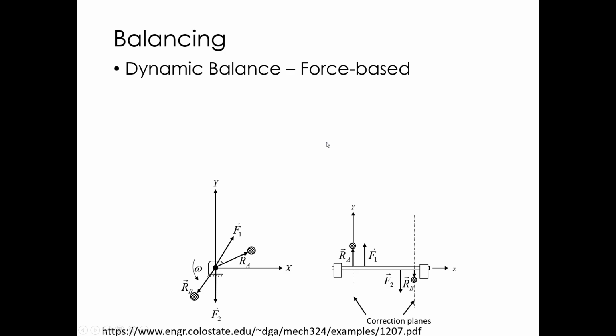Okay, force-based balance. The book does not do a good job on force-based balance, so I used an external resource here. You can see the link there if you want to see this PDF. But this is more useful. Force-based balance is how your tires are balanced. When you take them to a tire shop and they put tires on a balancing rig, this is what that machine is doing. If you're trying to balance a turbocharger impeller, this is what you do. If you wanted to make your own balancing rig, this is the math behind the scenes on it.